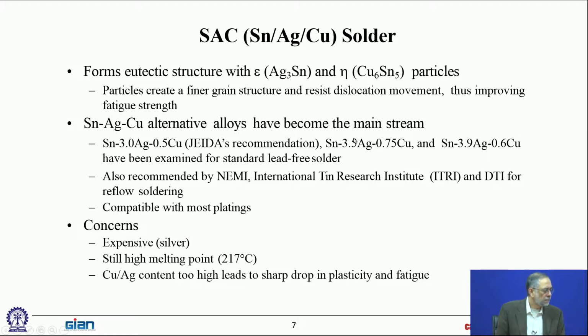Okay, so here are some of the early, commonly used solders. The early solders were of this range. This is eutectic. This is the ternary eutectic. So when we look at the tin, silver, copper phase diagram, you'll find that that's the ternary eutectic, but there are problems with that. When you have that much silver in there, you get excessive silver tin intermetallics, and over time we have found that that causes a lot of reliability problems.